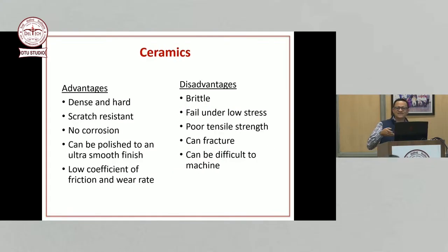So advantages and disadvantages of ceramics: they are dense and hard materials, scratch resistant. Again, you can think about that plate. Usually they don't scratch very easily, right? They do not corrode very easily, can be polished, low coefficient of friction. But disadvantages are they are brittle, they fail under very low stress, they have poor tensile strength. You can think you cannot apply stress and have it get elongated. They can fracture very easily and can be difficult to machine.